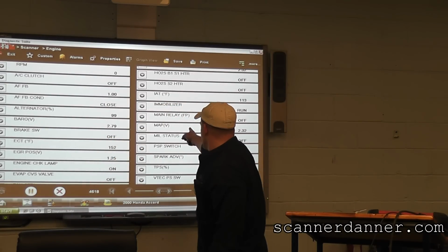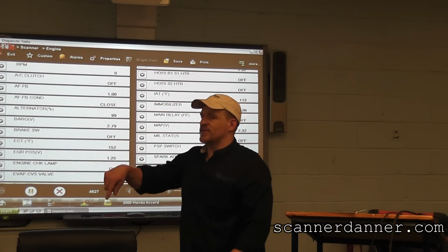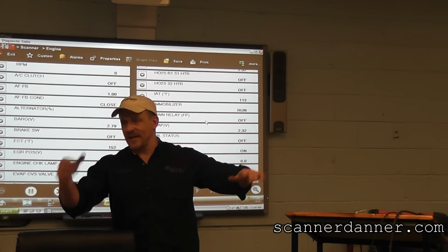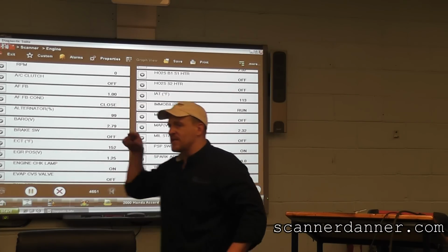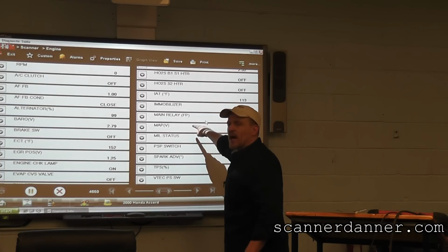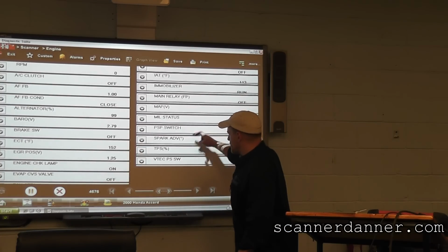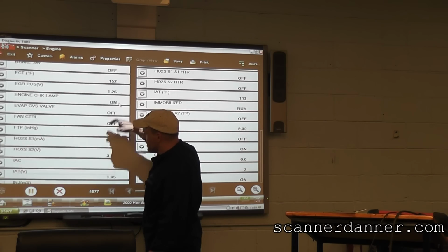And the reason the MAP voltage would be dropping is just because the wiring design of the TPS is different from the MAP, and that's what's causing that. It's not that the TPS voltage would start high and drop low on this vehicle. It's the other way around. Do we have TPS voltage, or are they only giving us percentage?